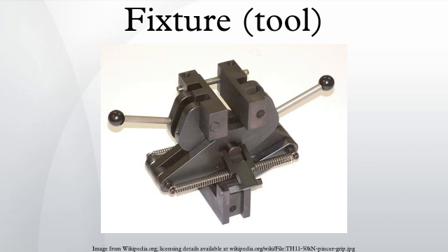Fixtures also allow for a higher degree of operator safety by reducing the concentration and effort required to hold a piece steady. Economically speaking, the most valuable function of a fixture is to reduce labor costs. Without a fixture, operating a machine or process may require 2 or more operators. Using a fixture can eliminate one of the operators by securing the workpiece.